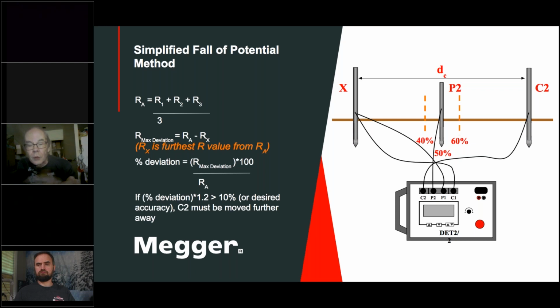It goes over to the other connections to the electrode, to the ring, or to the grid, and it just circulates back to the tester. And you got a beautiful low reading because there's nothing in there but metal. And that's essentially a short circuit. And the reading it gives you is just a continuity test of the grid. It doesn't mean anything. So those are the two main problems with using a clamp-on.